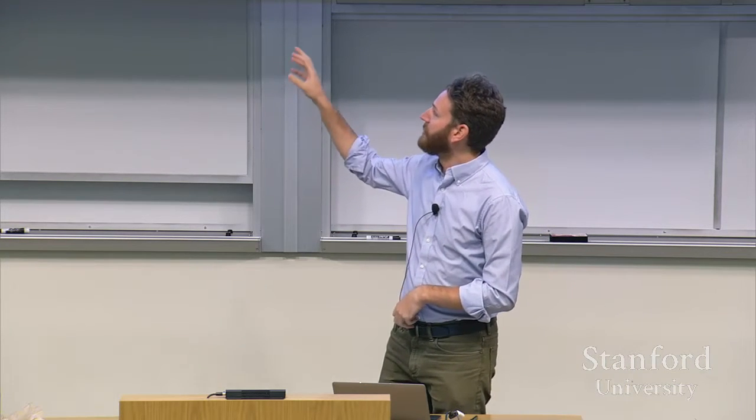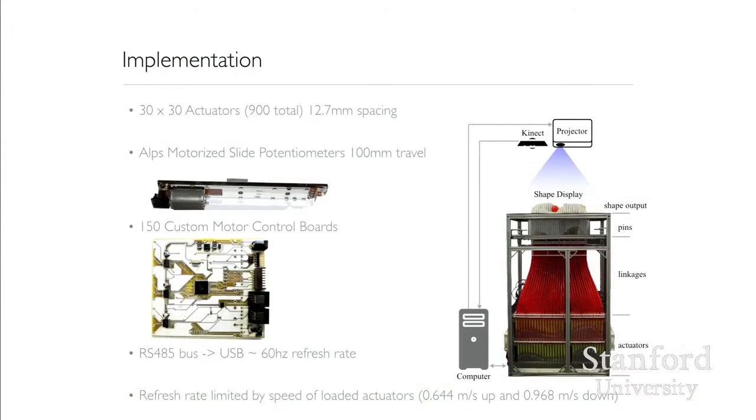Then we developed these custom motor drivers, and it's all connected over this RS-485 bus, and we can update it at 60 frames per second, although the motor speed, as I mentioned before, changes things. Then we have a depth sensing camera from above to track input, and we can also sense the position of the pins for interaction.